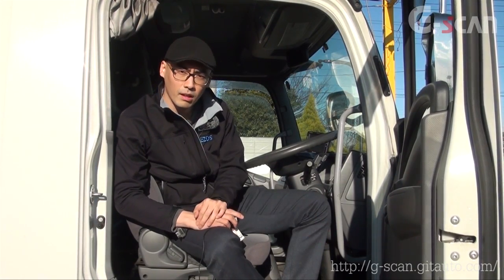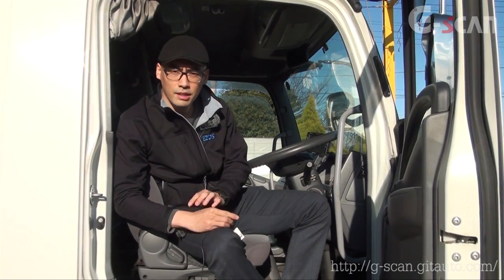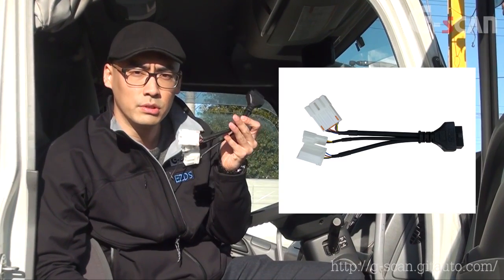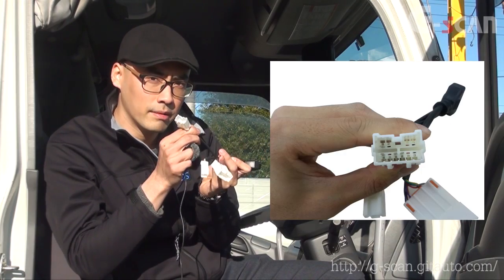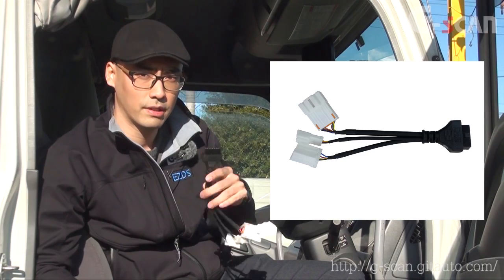We have found the data link connector location. Now we need a special adapter for some models in order to communicate with Isuzu commercial trucks. This adapter is especially designed for Isuzu commercial trucks. It's got 20-pin, 10-pin and 3-pin connectors attached in this adapter. This adapter does not come with the standard kit. So please, if you need one, contact your local distributor for more information.